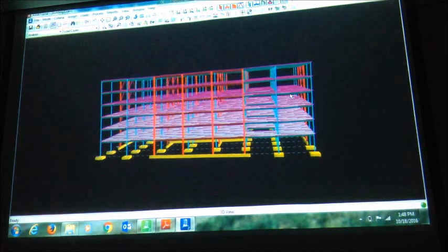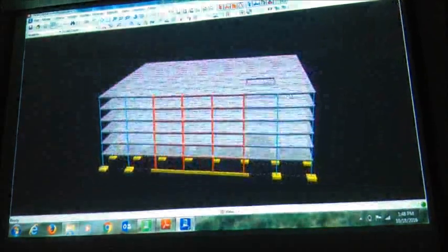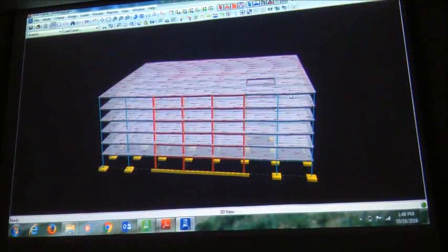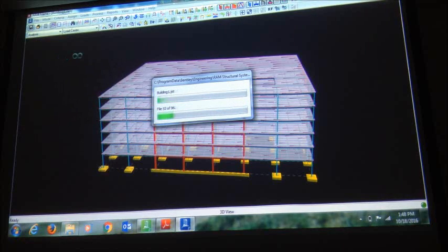Now it's okay. The reason was beam to column connections were pin connections. So it has to be, moment frames cannot have a pin connection. It has to be a rigid connection. Okay? Sorry for that. Anyway, so let's see the dance now.